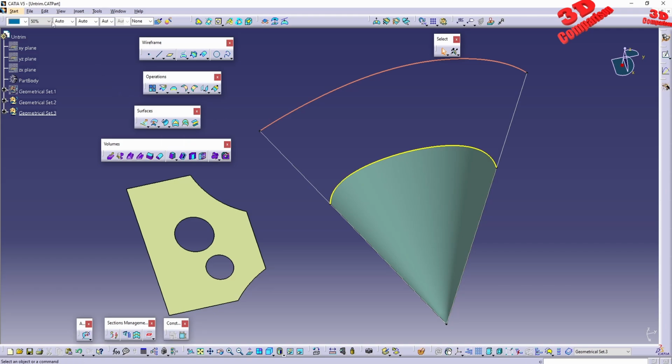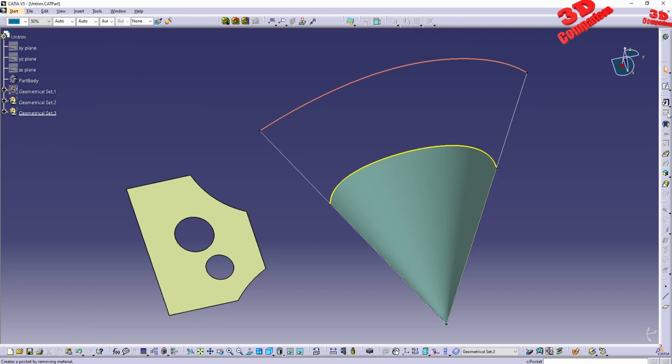But for some reason, if you are familiar with CATIA part design, they decided to use a different naming. For example, for revolve, they added shaft. And for extrude, which is common within all CAD solutions, Dassault Systèmes decided to use the naming pad for this. And in order to do an extrude cut, they decided to use pocket.